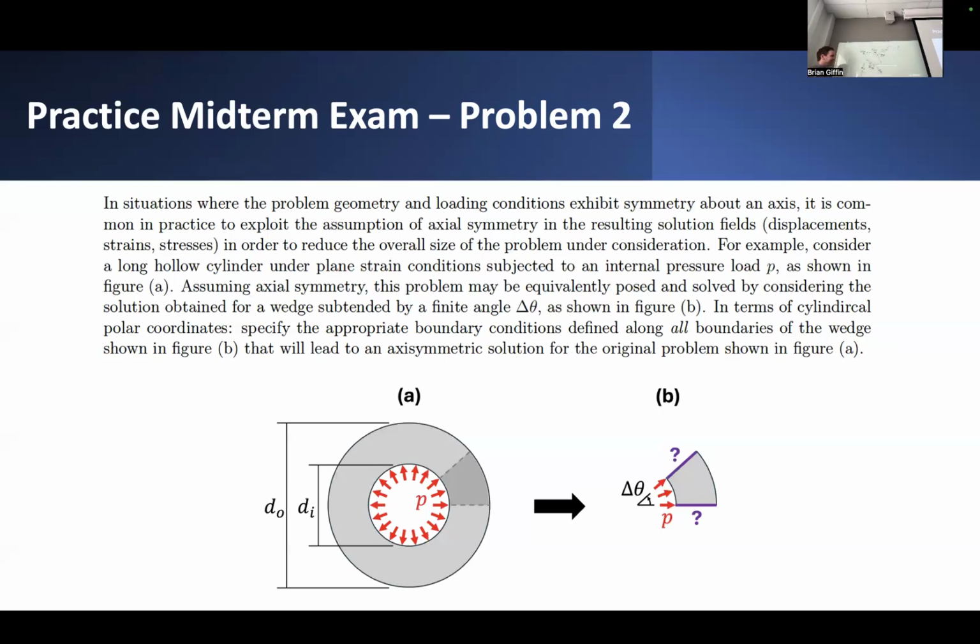But we have to be kind of careful here, because the sign convention for stresses, at least in this cylindrical polar coordinate frame, indicates that a positive value of sigma RR is actually pointing inward. If we're looking at a chunk of surface area whose normal is pointing not in the outward radial direction, but now in the inward radial direction. Basically, what that means is this arrow corresponds to the positive value of sigma RR. So if sigma RR is positive, it's kind of like we have a tensile stress that's causing this whole thing to expand.